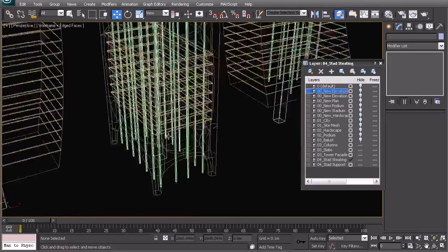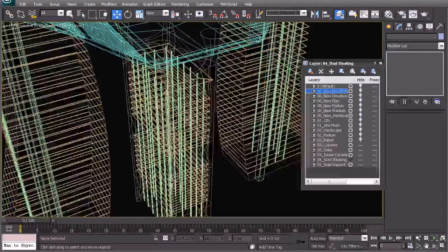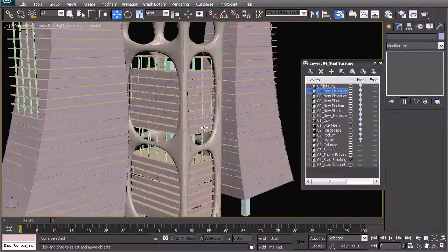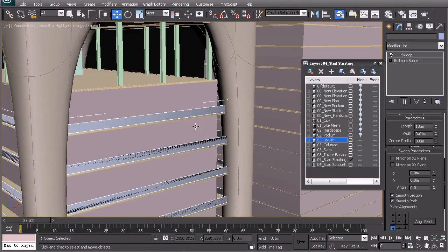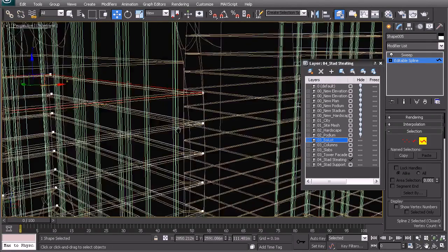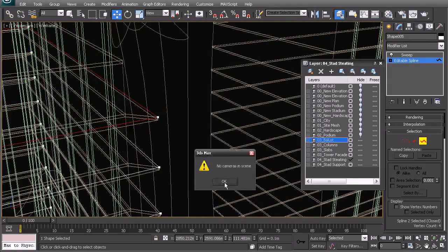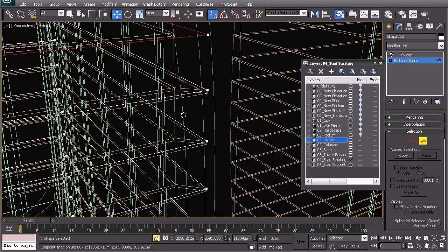And since we are showing the sky garden, you may want to add in the other columns just so that you can see all of them coming through in the middle there. Now let's have a look at the balustrades, and I believe we'll have to do the same thing. We have to copy one more balustrade up. Let's go back into the spline level, and here you can use the reference from directly below, and pressing spacebar, snap, and shift, we're going to shift that upwards.